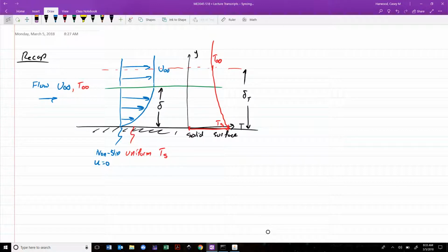So inside of this boundary layer, we said, for convection to occur, if thermal energy is going to leave this solid surface, conduction carries it up to the surface, and then in this tiny, infinitesimally thin layer of fluid that is stuck to the surface by this no-slip condition, it has to cross that thin layer by conduction as well. So we ended up with an energy balance that said it gets into the fluid by conduction, and from there, that advection starts to take over.